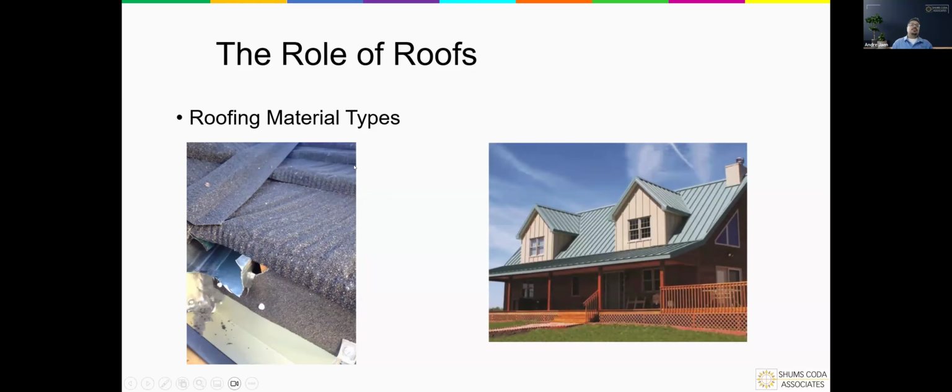And again, that changes some of the things about our fire classification. It changes things about how much ventilated space is going to be underneath that decking. It changes things about the plan for airflow, and maybe some of the other materials and the best way that a contractor wants to use towards properly installing that roof or not. And on the left, we can definitely see a concern on the left-hand side that is pretty rough, all things considered. So, all right, I will keep on rolling here.